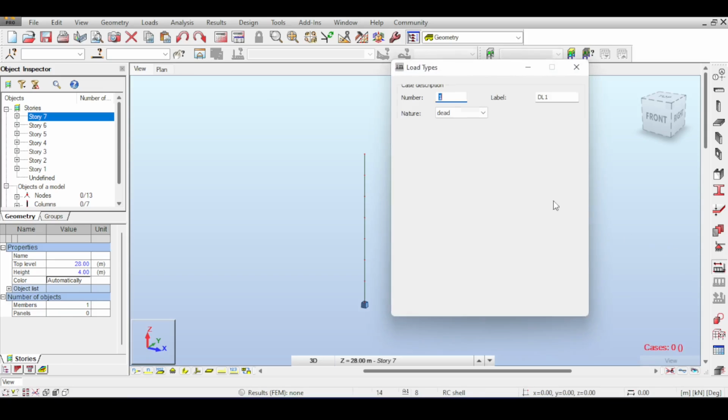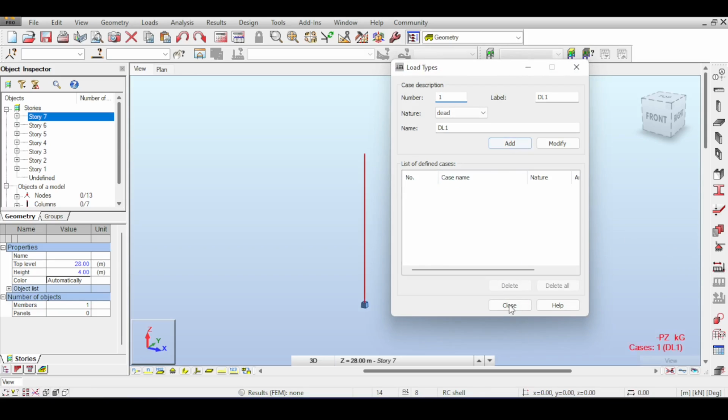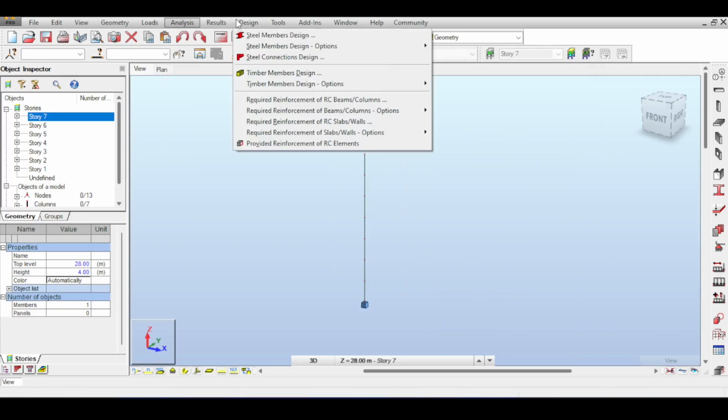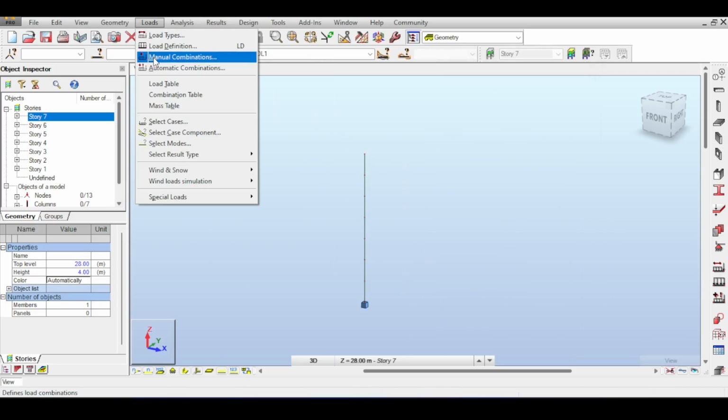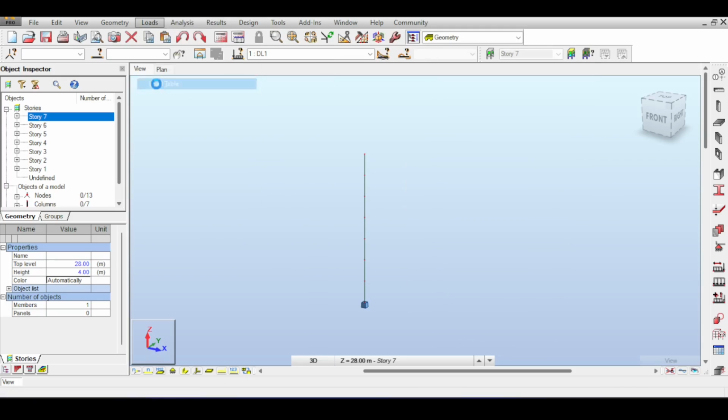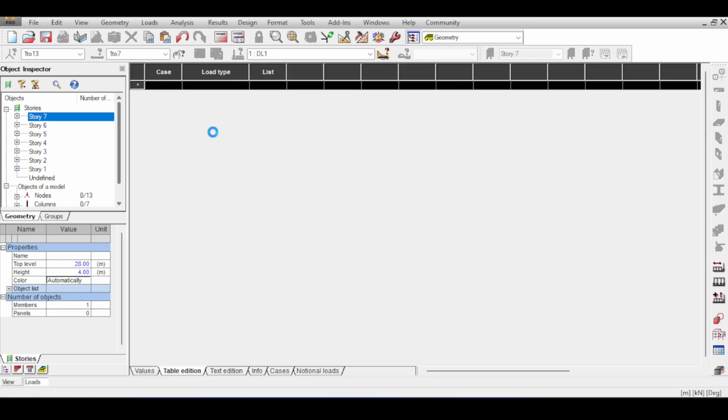I'm just going to open here a dead load case. This time I will delete the self weight because I don't want any P delta effects to be taken into account here. Of course, I never talked about P delta effects and nonlinear analysis. This is of course a very juicy and nice topic that I will be leaving for later.